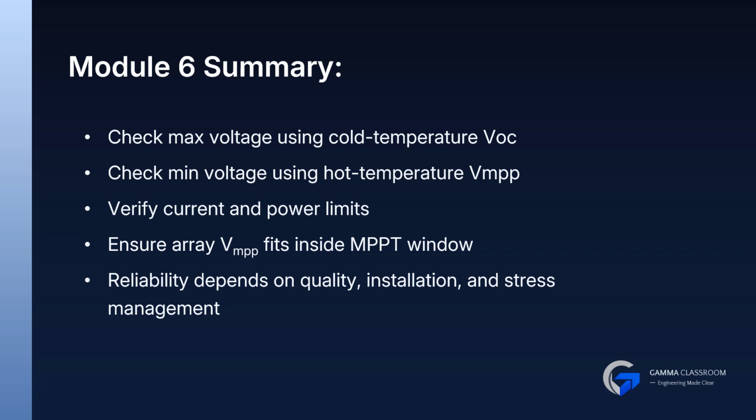Ensure maximum power point voltage fits inside the MPPT window. And remember, reliability depends on quality, installation, and stress management.